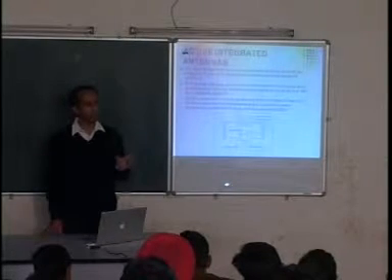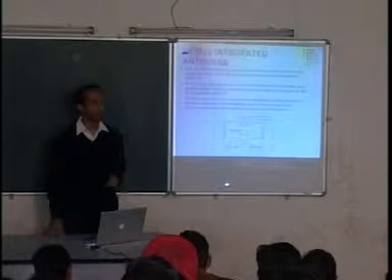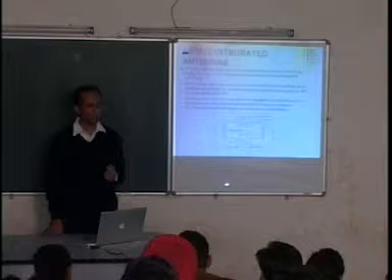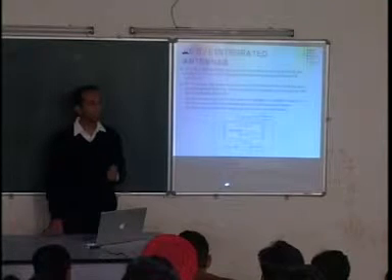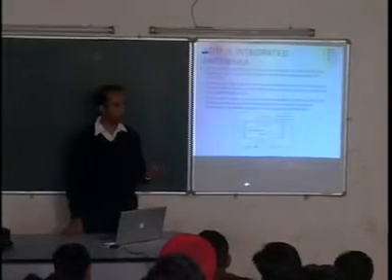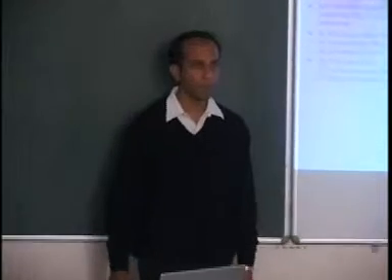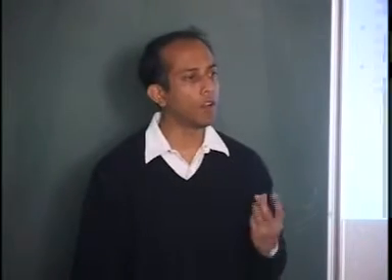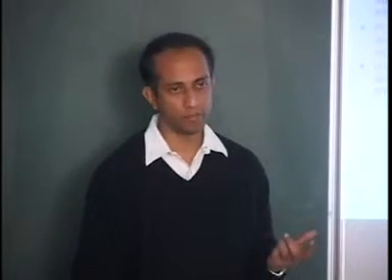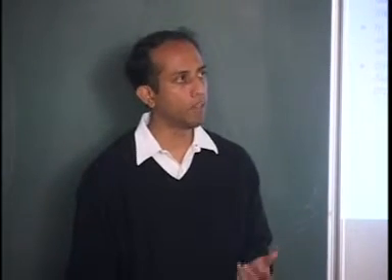If an antenna is doing that, but at the same time it is serving some other function, so this is called a multifunctional element, then it's called an active antenna. And typically this other function will be in the context of a nonlinear active circuit. That is not compulsory, but that is usually how it becomes useful.